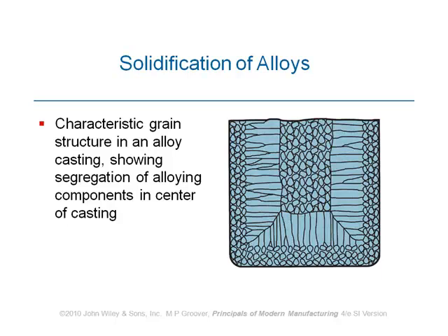Now, let's talk about the core of this particular grain. In the core of this grain, do we see more component of this or that? Which one? In the core of this grain, is the material richer in atoms of this or richer in the atom of that one? External one, right. Because it's the first point which solidifies.